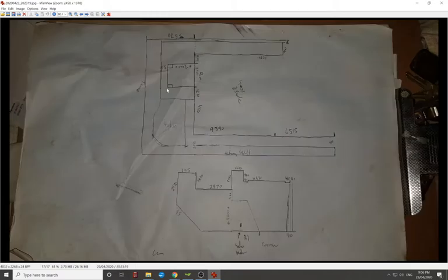So this is the mud map I came up with. I use this graph paper. It's an A3 graph paper with 2mm squares, and I just go out there and run my tape around the whole house and measure every side, square, square, square, and then measure the distance from the boundary. You see I've measured there. So I've measured from this back wall corner to there. It's 5970 to the back of the fence.